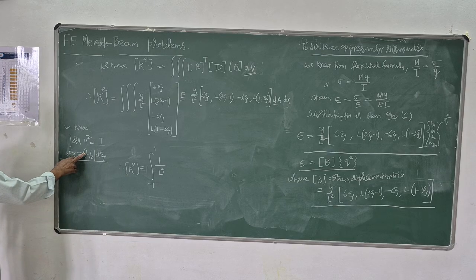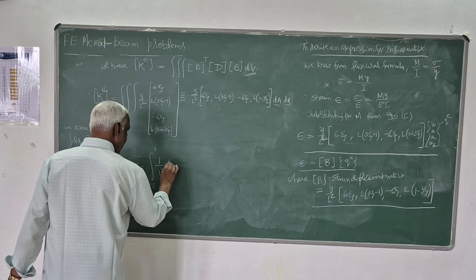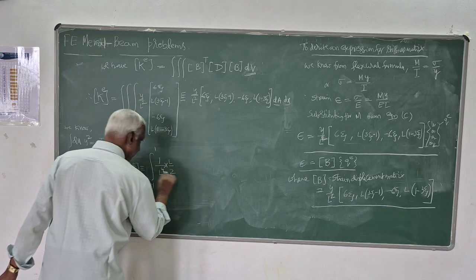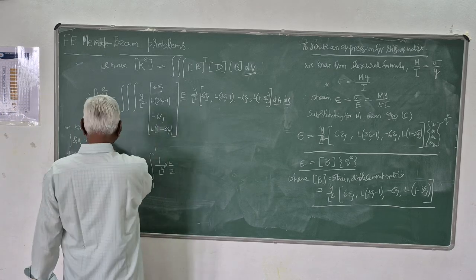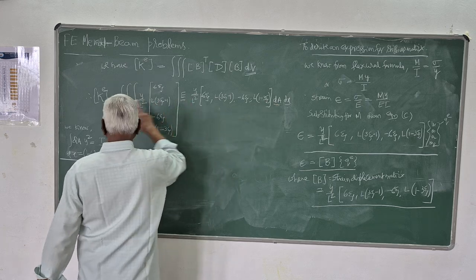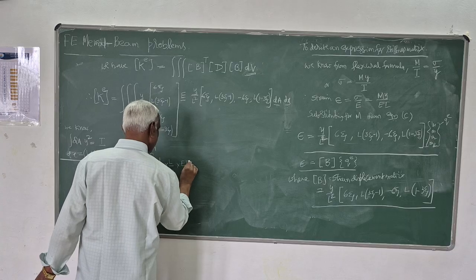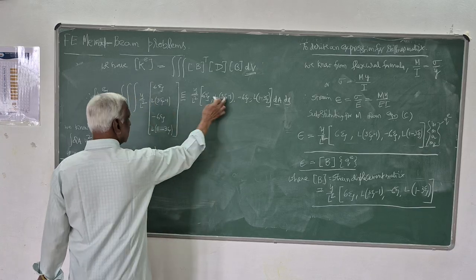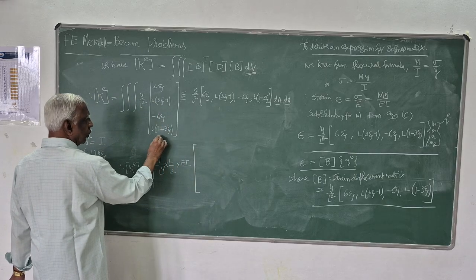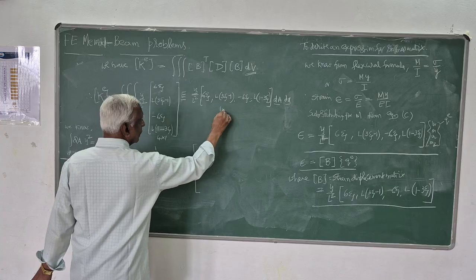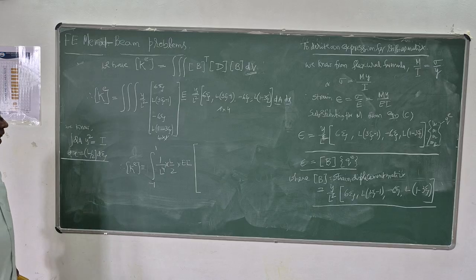and here it is L by 2 because dx is replaced by d psi, so I will write L by 2 into d psi. And this dA square is nothing but I, so I will get I into di. Then if you multiply this 4 by 1 matrix with this 1 by 4, you can multiply, and you will get a 4 by 4 matrix.